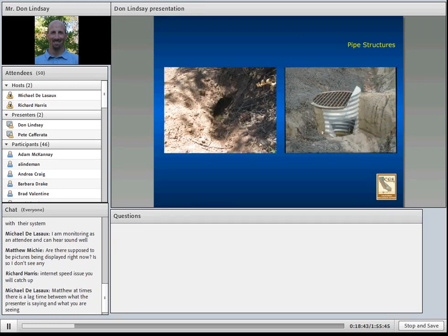In this photo, we have two examples of cross-drain pipe inlets. The inlet on the left is a typical inlet. You can see that this one is partially blocked by debris and difficult to see. The pipe on the right has a drop inlet structure. The drop inlet structure is expensive to purchase and install, but it provides benefits, including that it allows the cross-drain pipe to be buried deep in the road to protect it from damage.